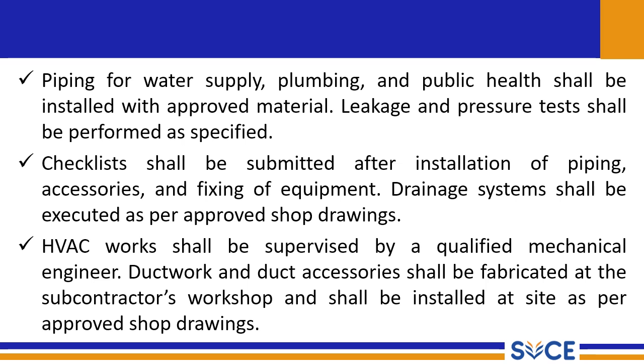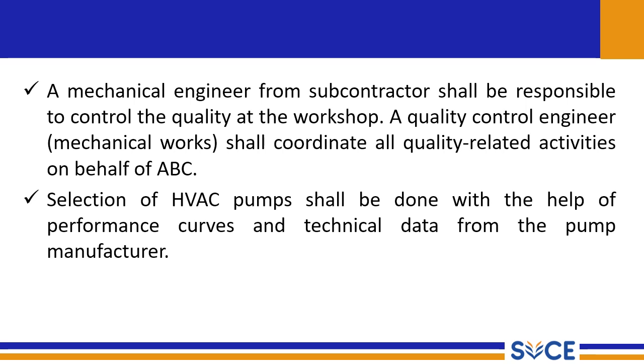HVAC work shall be supervised by qualified mechanical engineers. Duct work and duct accessories shall be fabricated and installed at site as per the approved shop drawings. A mechanical engineer from the subcontractor is responsible to control the quality of the work. The quality control engineer shall coordinate all quality related activities on behalf of the company. Selection of HVAC pumps shall be done with the help of performance curves and technical data from the pump manufacturers.